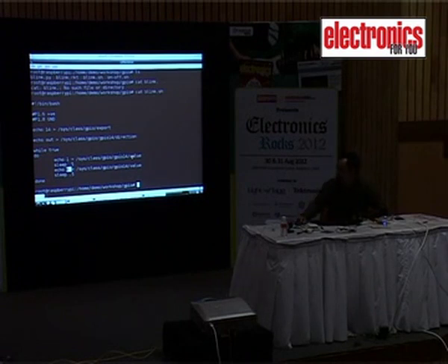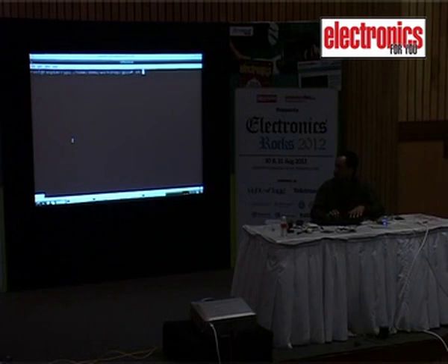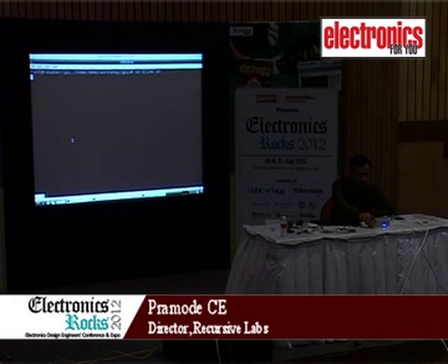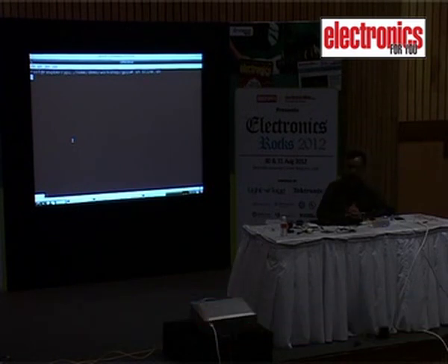You write a 1, the LED goes high, you sleep for 0.5 seconds. Write a 0, the LED goes low, and again sleep for 0.5 seconds. Do it in a loop and you have a simple blinking LED program. Let's try running it. And you can see the output here. The LED is blinking. Just a few lines of shell script, and you have control over your I/O pins.